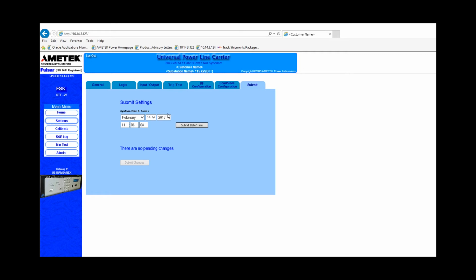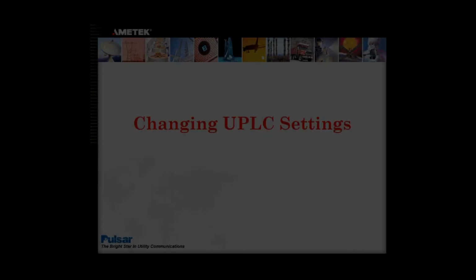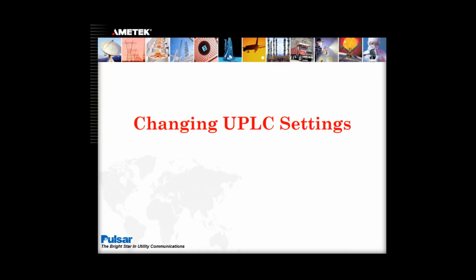The date and time settings are not instantaneous nor saved in the UPLC settings file. Once you make a change, you must press the Submit Date and Time button for the change to be programmed into the connected UPLC. If you exit this page without submitting the date and time, then it will not be programmed. Now we will discuss how to change UPLC settings.